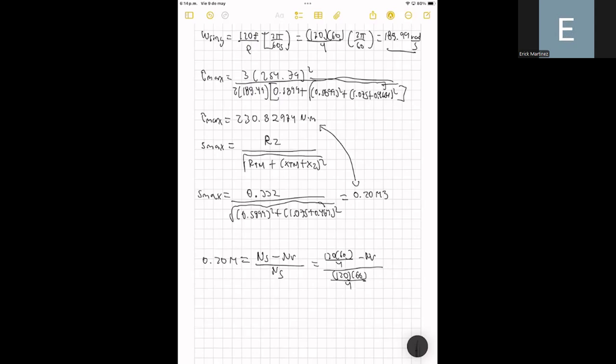And if we substitute for the rotor speed, the result is 1,437 RPM. Also, we can convert this in radians per second, but you can express this in revolutions per minute. Again, this speed is related to this slip and also to this maximum torque.